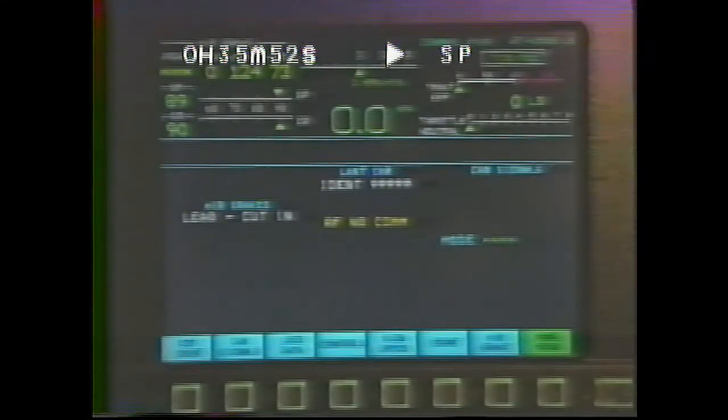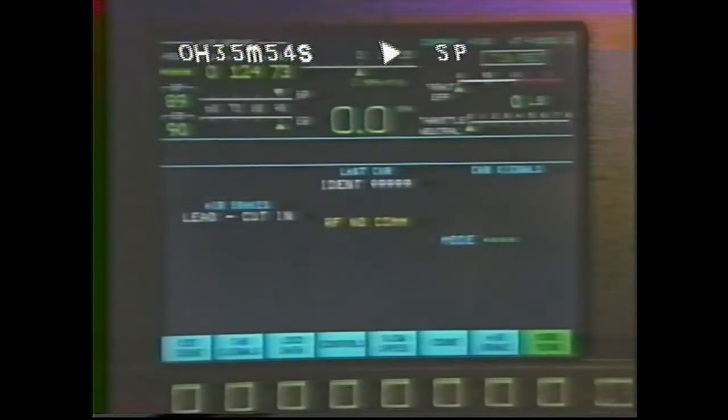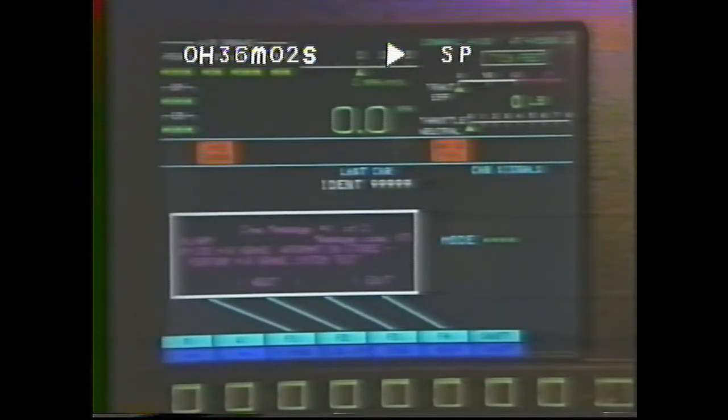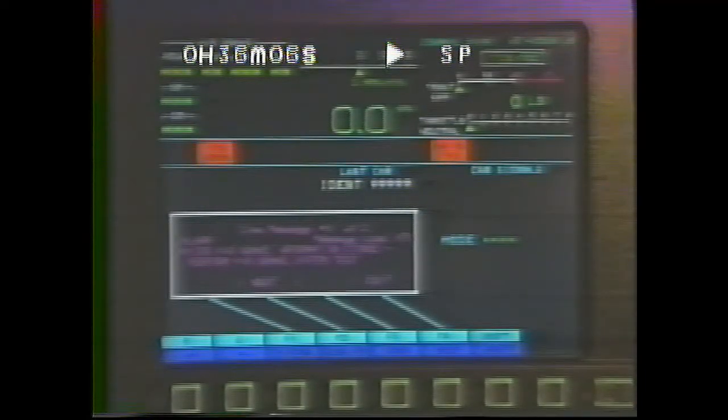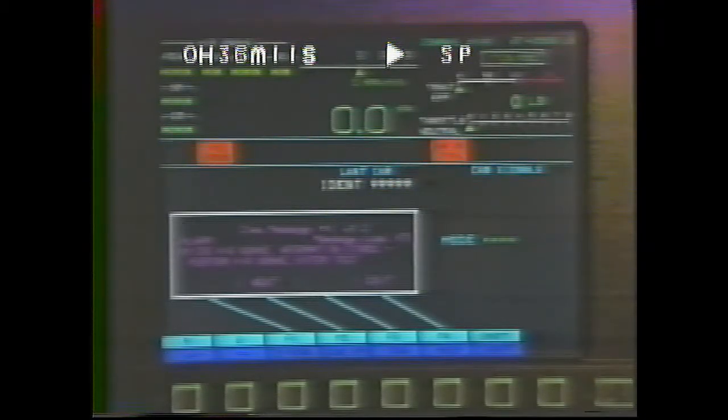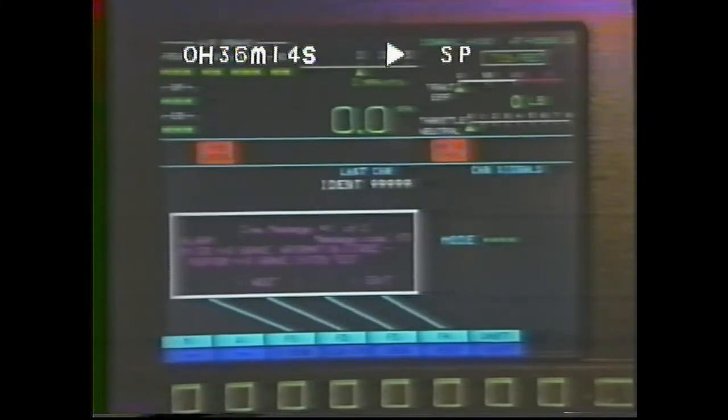Anytime the Epic air brake system is powered down or de-energized, an alarm will sound, the brake fail will light, the air brake system will automatically go to trail, and the pneumatic backup system takes over. However, the computer holds in memory the last air brake setup that was in effect prior to powering down. When the system is powered up, the screen will show the last air brake setup. The data fields of the air brake portion of the screen may show asterisks until the computers have gone through their startup tests and have detected the status of the air brake system.